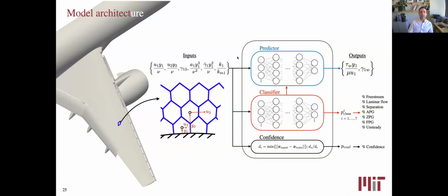Then I will use these as inputs. What matters is not the input itself, but the non-dimensional numbers that you can create with your inputs. So the units shouldn't matter. The way of getting non-dimensional inputs is that you have to cancel out the units. So you can think of how many parameters you have. We have distances, velocities, this mu is the viscosity, and the ratio of density. And with that, we create a set of inputs. In this case, we have 6.